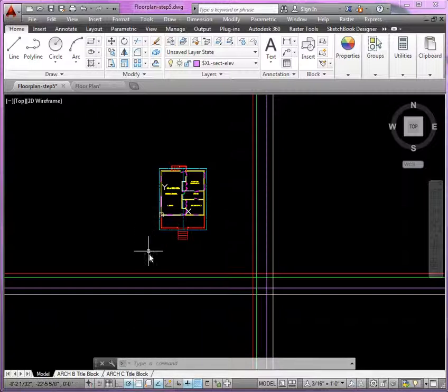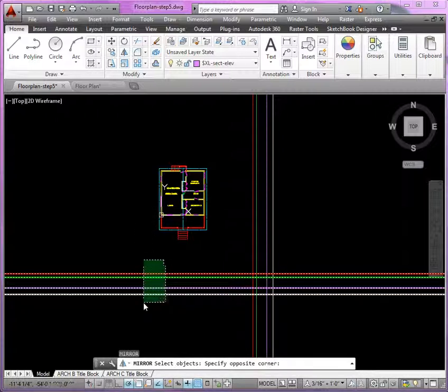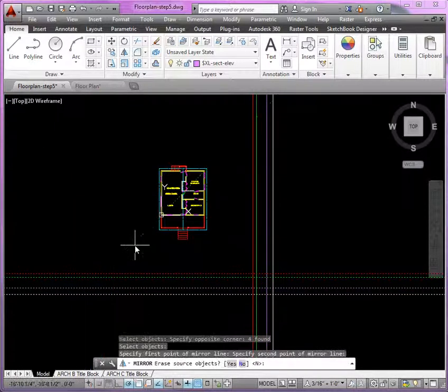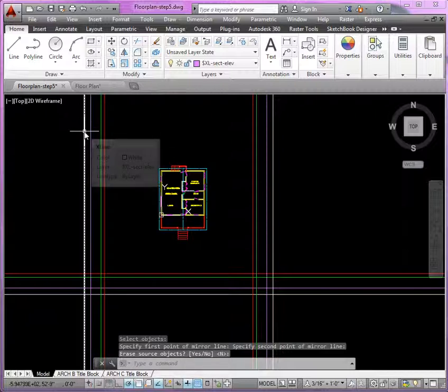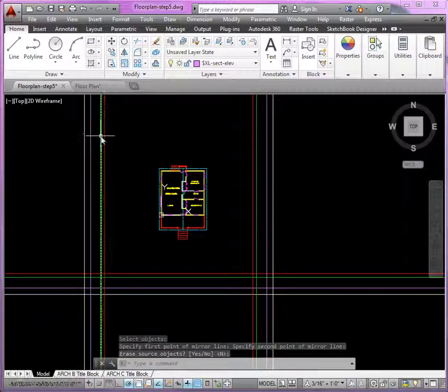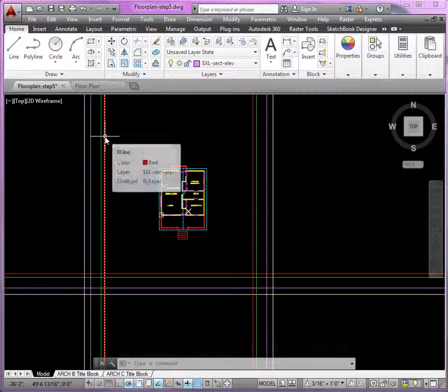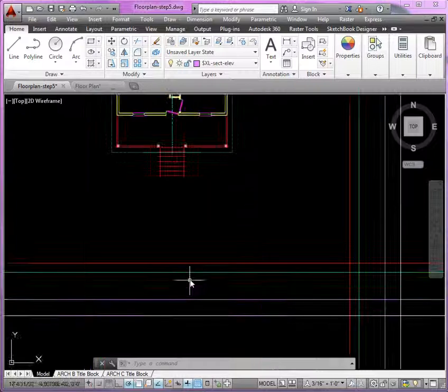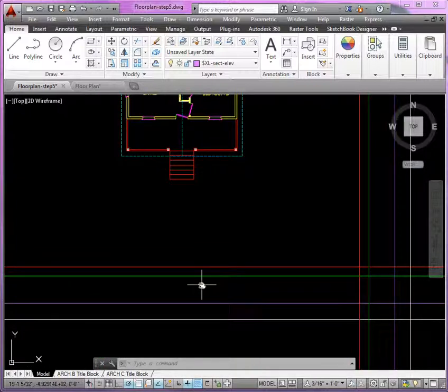Okay, and if I wanted to do the west elevation, I could do the same thing. I could just simply make a mirror copy over here. And you could see this is still the ground, this is the floor, header, and then the roof plate. So imagine if you have the 3D object here and you unfold or flatten the box. All right, so let's just focus on the south elevation for right now.